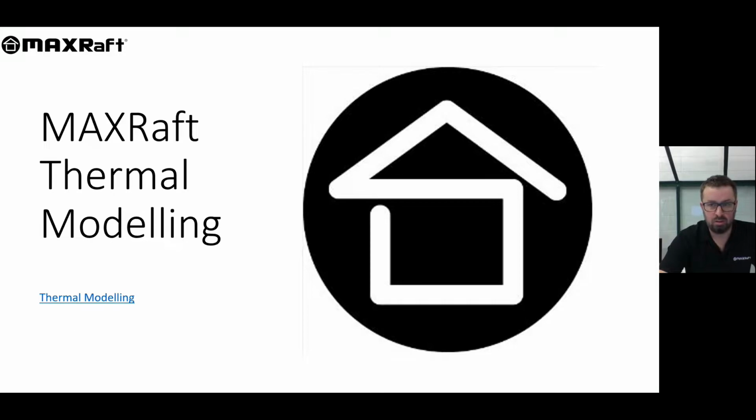Okay, so our thermal modeling document is available on our website under the resources section. It was completed by MAXRaft and Sustainable Engineering Limited. All of our thermal modeling is based on the use of EPS insulation rather than XPS. As a company, we prefer to use EPS as it's manufactured in New Zealand and we're able to recycle it easily, and use recycled content in the product. XPS is obviously an imported product, isn't recyclable, and is a bit more expensive.